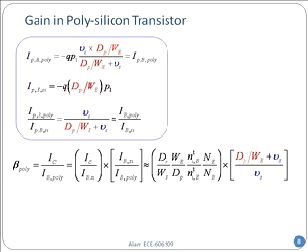But because of the polysilicon and silicon, the suppression by polysilicon, I have these extra factors on the very end, which have this red diffusion coefficient and small blue surface recombination velocity. So that ratio, I'm just plugging things back in from over the top, from the table or from the box on the top.